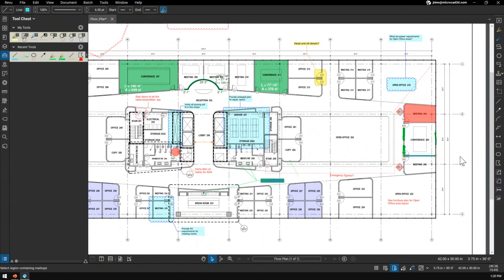So right here, let's say that the cloud that I want to create is going to be like this. We can customize the colors that we need. We can even customize the border type that I need for my cloud, right? I can customize the size of my cloud, right? You can see right here the level of precision that I might need. Maybe in your company you have small clouds, right? Right here you can add the fill that you want, always changing that opacity to have a cooler look.